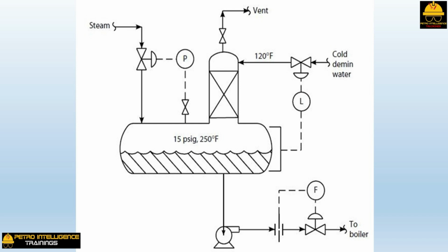As noted above, liquid hydrocarbons must be removed by a clay polishing step to prevent oil accumulation in the deaerator, or laydown of a non-wettable film on boiler tubes. In the event that there is too much residual oxygen in the deaerator effluent, the flow of vented steam from the top of the deaerator should be opened. However, often there is no vent valve, but just a fixed orifice vent. Or perhaps the supply steam control valve is 100% open.